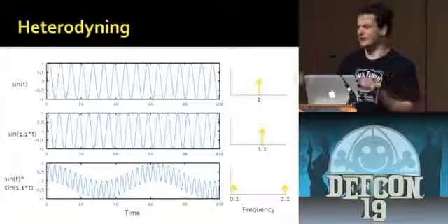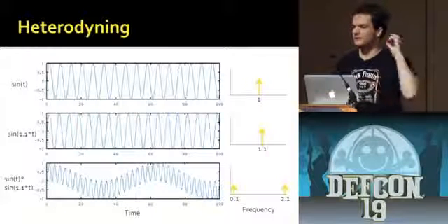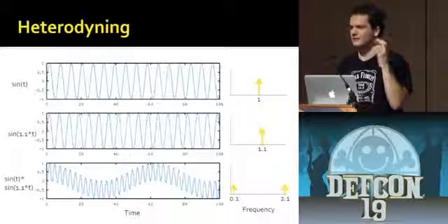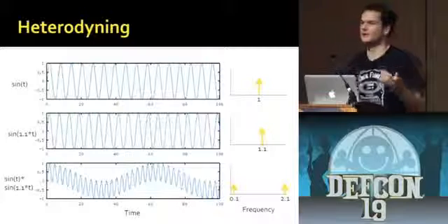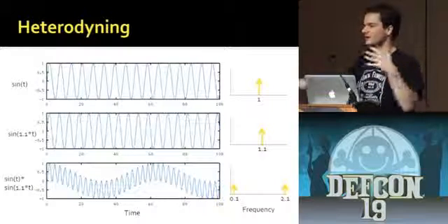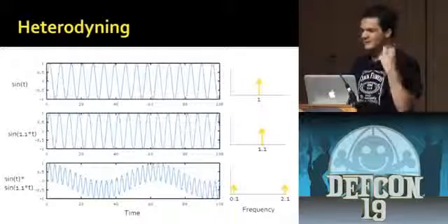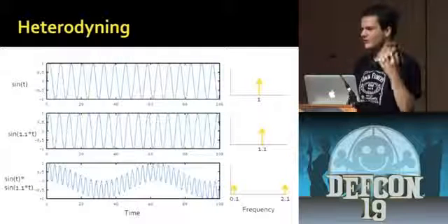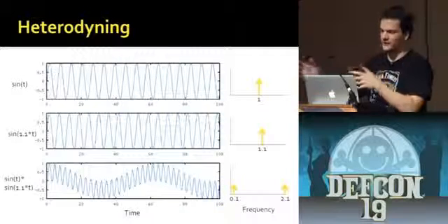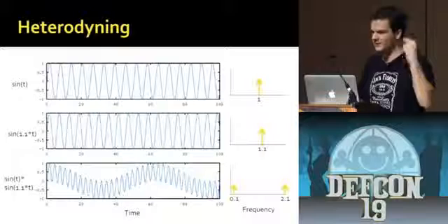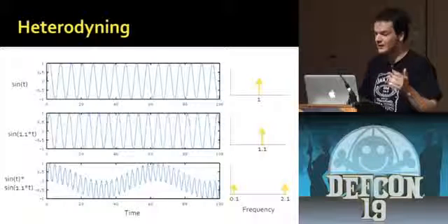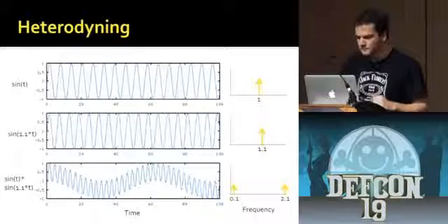If you have a bunch of case fans in a computer, for instance, you can get those really annoying time-varying tones. So if you have something running at 6,000 RPM and one running at 6,010 RPM, you have a 10 RPM signal that's being generated acoustically between those two things. So you have some faster signal and then you have this slower one, and that's going to give you that beating tone, which is really annoying. That's exactly what's happening there.